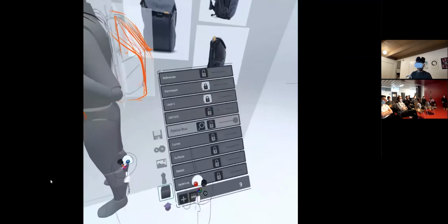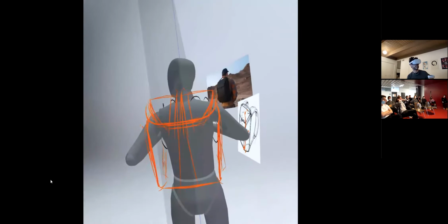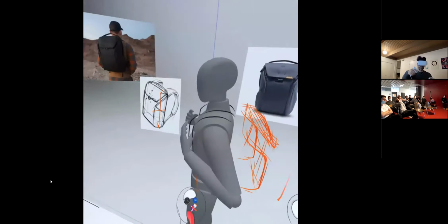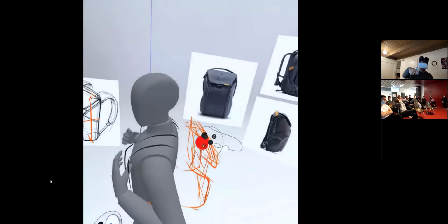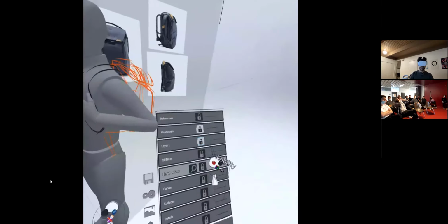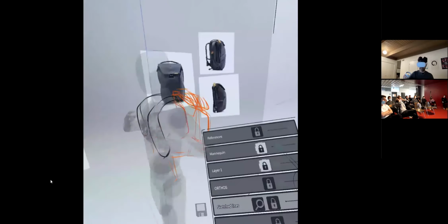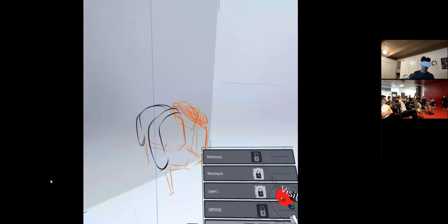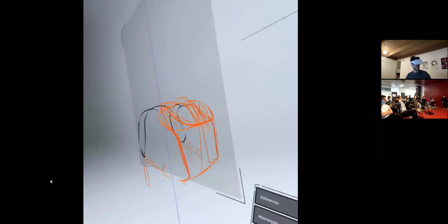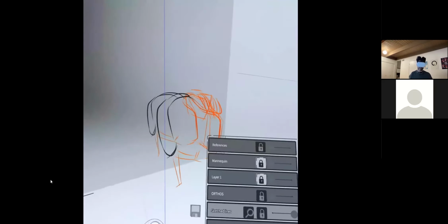So this is what immediately replaces a two-dimensional sketch. It's a 3D sketch like this. It can be messy. I suggest that it is, because you're really just trying to get a gesture of this object and start to visualize it and see it. I suggest keeping everything on separate layers so that you can toggle the visibility on each on your own, and it doesn't really interrupt your idea. Here you go. That's basically the shape of it.